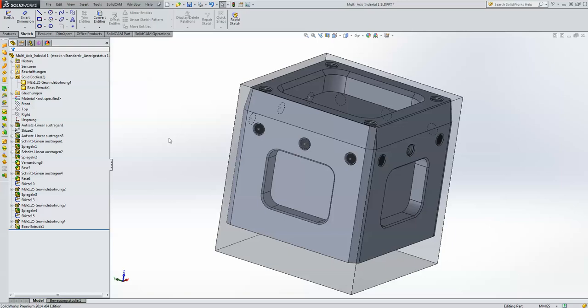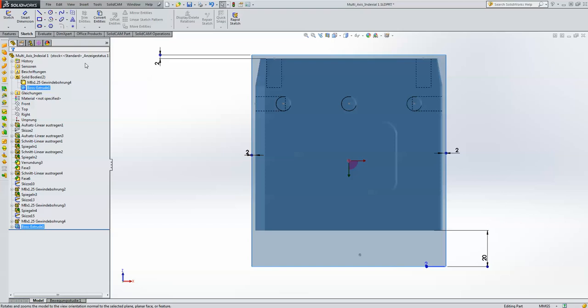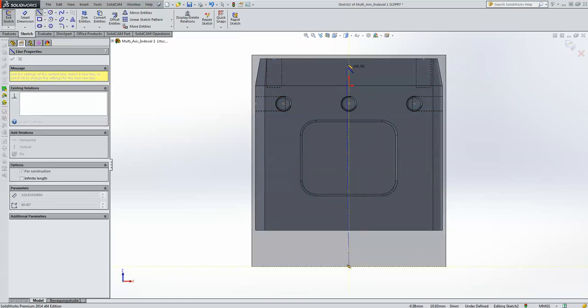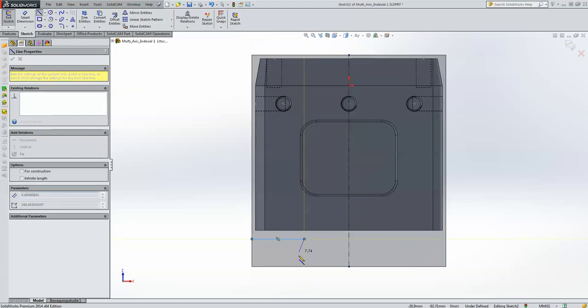Okay, let me just continue now with the actual building of the stock. I'll choose this side over there, and what I'm going to do is put the actual dovetail at the very bottom. So we'll start a sketch, and I'm going to start with a center line going from the center over here, all the way up to the top, and then choose a regular line, and I'll start from this edge of the stock over here, going to over here, giving the shape of my dovetail all the way to the bottom over here, to that corner, and back up to over there, closing it all off.